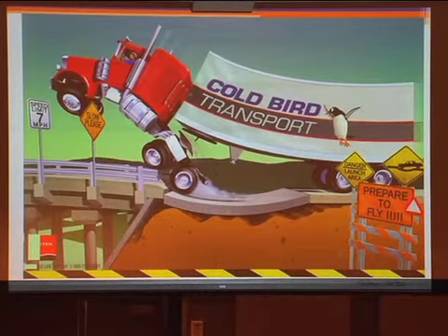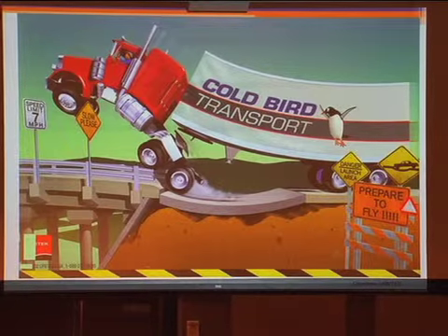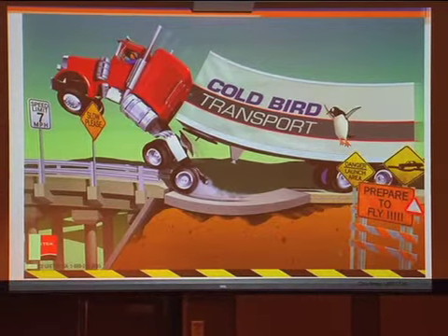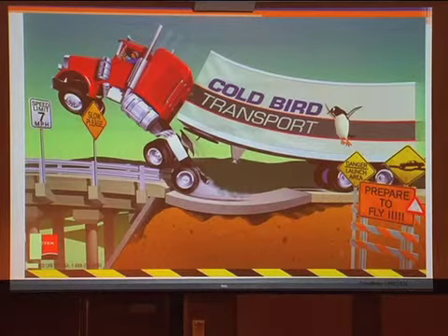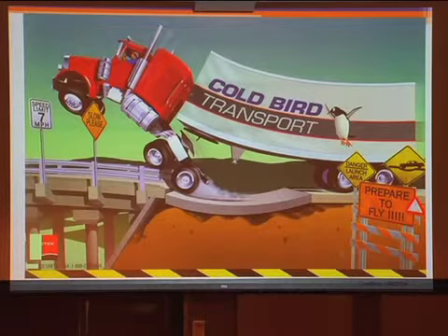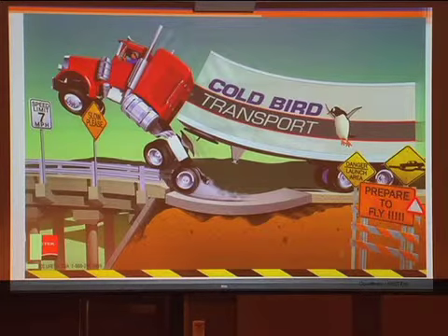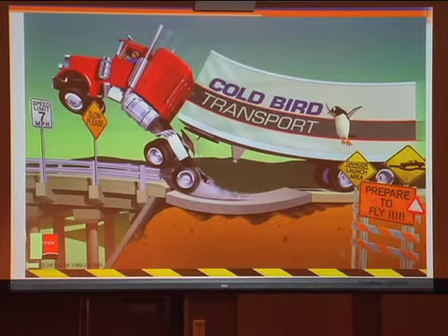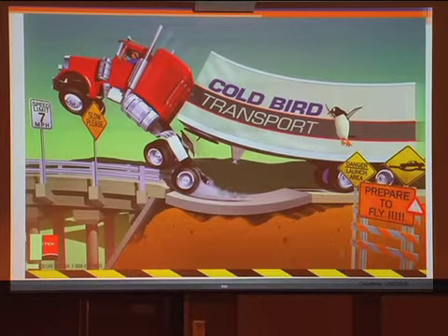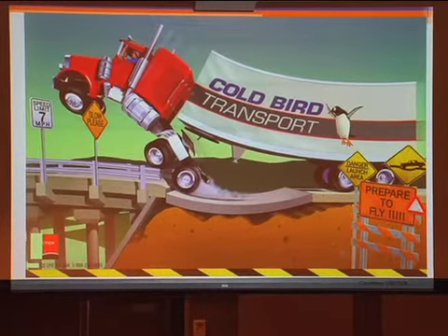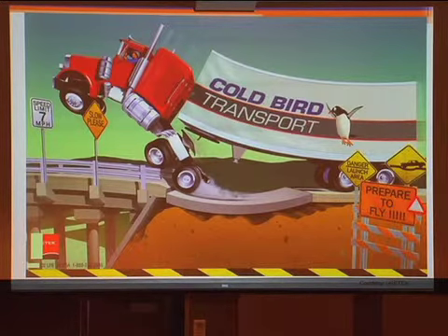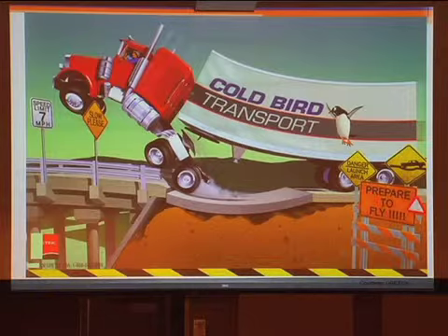We know it comes from subgrades, the natural subgrade foundations underneath your fill material. A lot of times the fill material itself will consolidate with time, because even though we supposedly use a select fill, sometimes we have fill that has high plasticity. So they tend to experience settlements, primary consolidation type. You do have erosion, side erosion, rainfall and all others that can take away material on an embankment, on the side slopes. You will see sometimes washing of fill material.